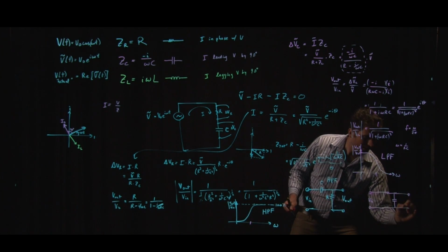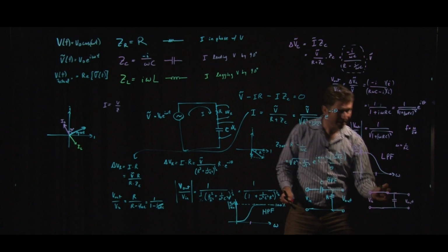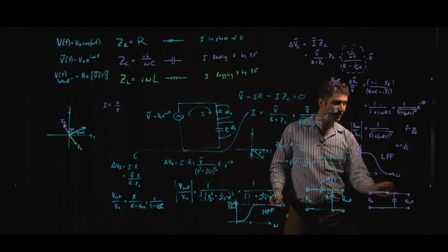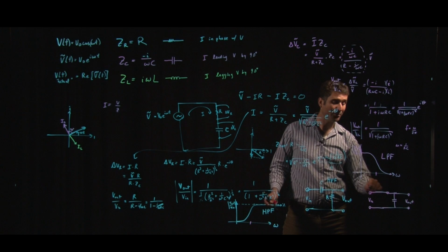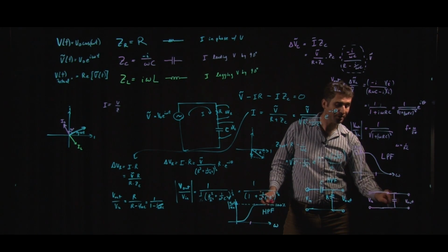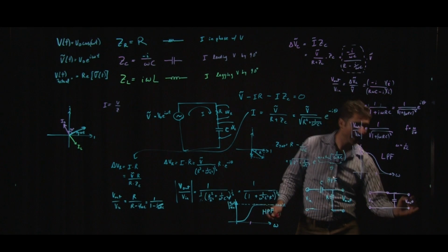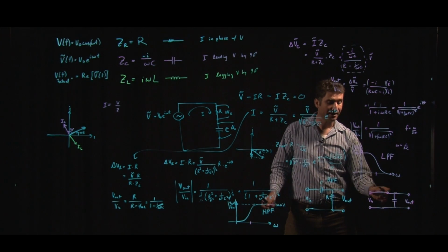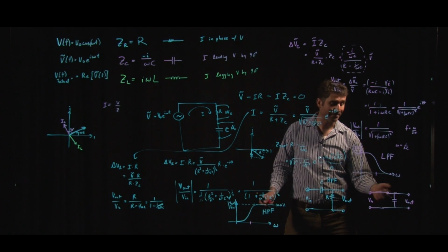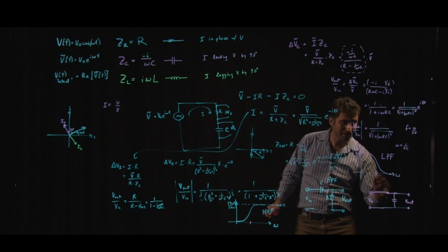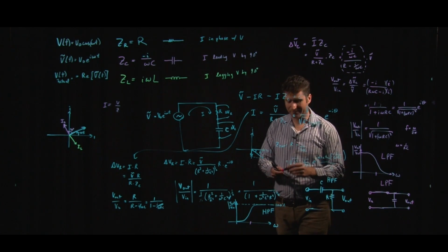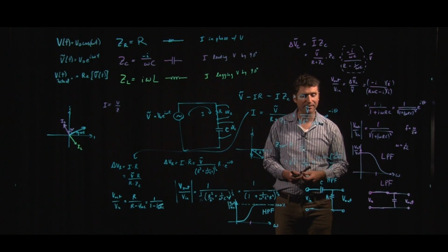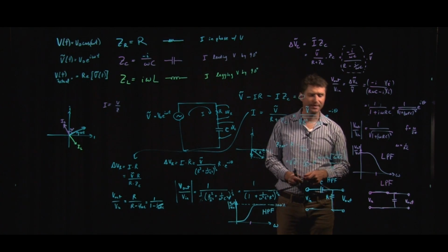And so here, if I measure V out, now if I had low frequency components, those current components are going to be able to go through, whereas if I had high frequency current components, you could imagine that they're going to short to ground across the capacitor, so we wouldn't actually have a measurement of any voltage drop across the capacitor at high frequencies. And so this is a kind of a symbolic diagram for a low-pass filter, something that shows up very commonly throughout all types of circuits in electronics.